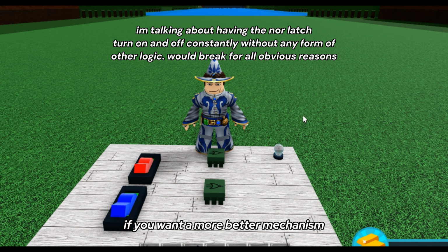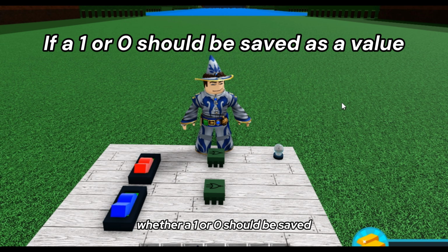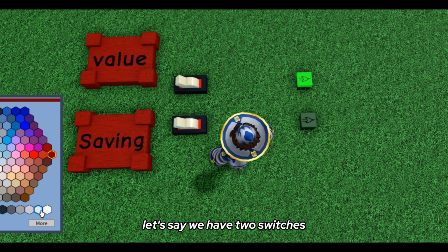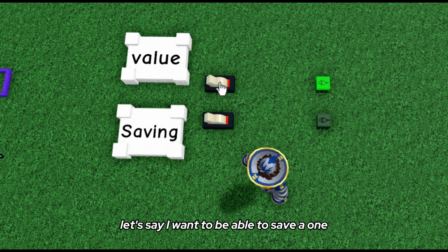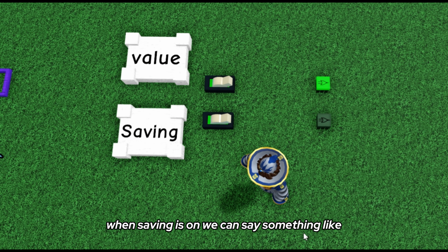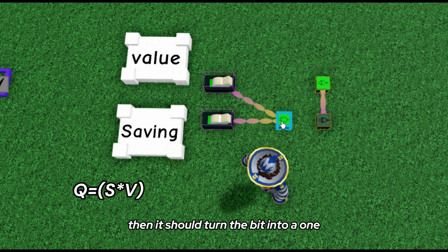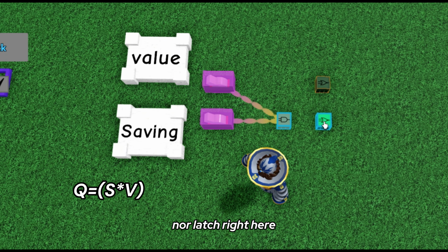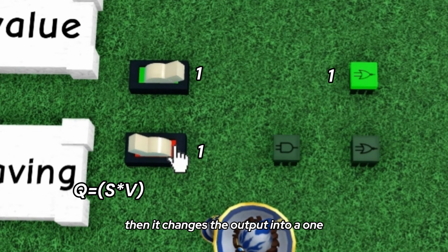If you want a better mechanism, it would require more logic, and it would allow us to specify whether a 1 or 0 should be saved. Let's say we have two switches, one for value and one for saving. Let's say I want to be able to save a 1 when saving is on. We can say something like, if save and value is on, then it should turn the bit into a 1. Let's also plug the AND gate into the bottom NOR latch right here. Now if value and save is on, then it changes the output into a 1.